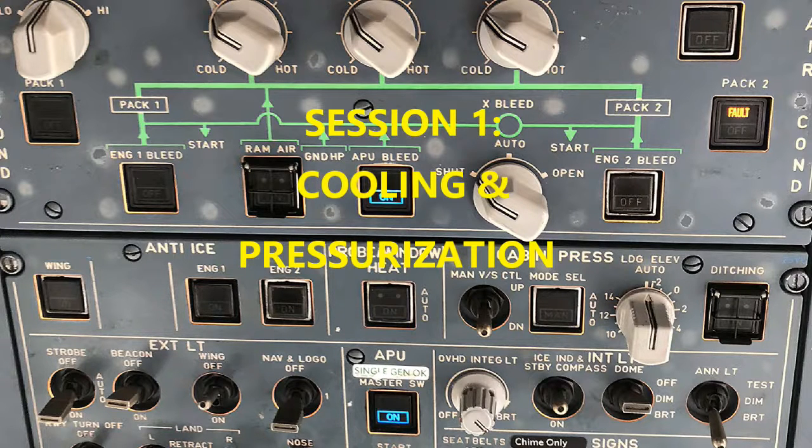That system test continues for not more than 300 seconds, just to give you an idea. And then the monitoring is a continuous monitoring. After power is supplied to the system, it's going to constantly be checking for faults. If it detects something, the system activates the backup, and that's going to discriminate which LRU is faulty.